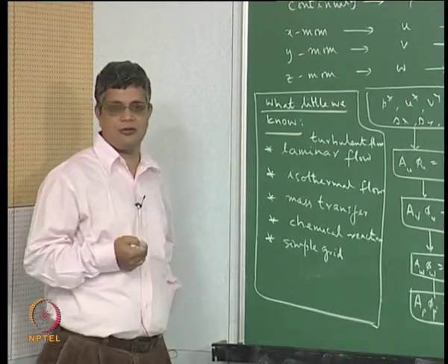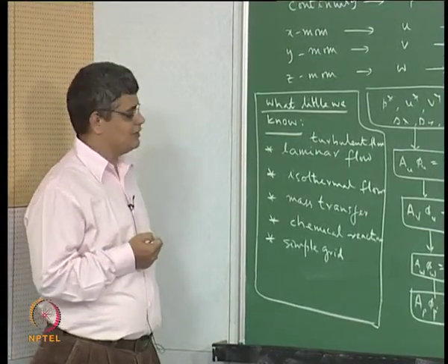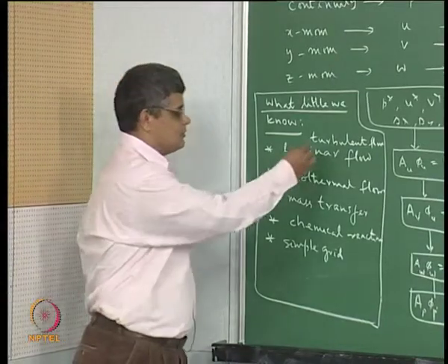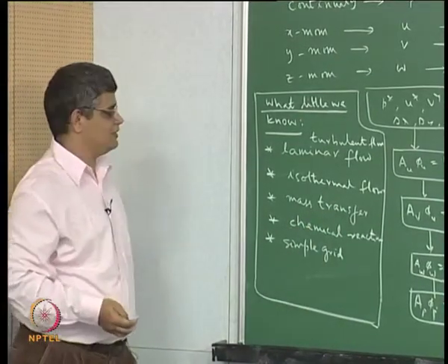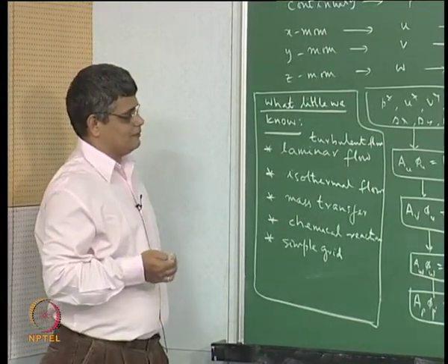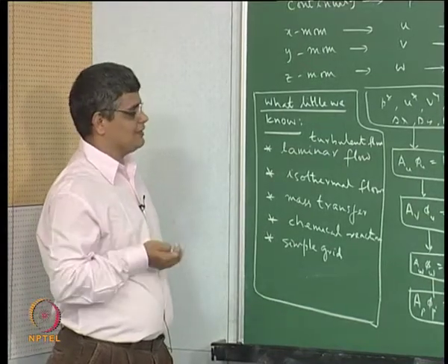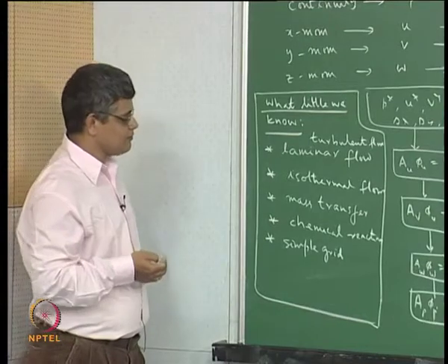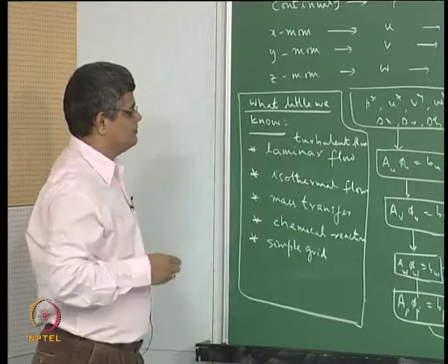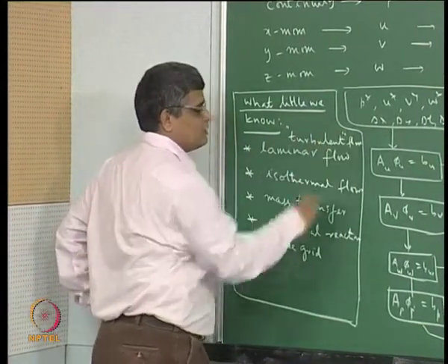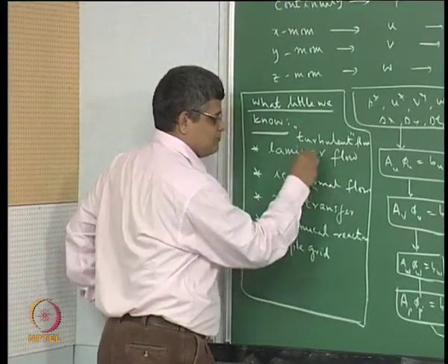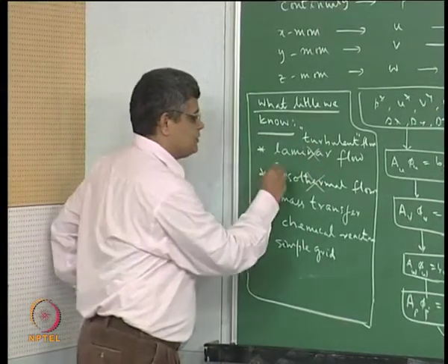Definitely it is one of the challenging problems, and definitely it has a lot of difficulties associated with it, and especially when you couple turbulent flow with chemical reactions, then it becomes really a humongous problem which cannot be addressed in its entirety in all its complexities that are typically found in practical applications using CFD. Okay. So we need to make approximations and we need to bring in models. So we need to see how we can deal with turbulent flow within the context of CFD, and we can easily get around this problem of isothermal flow by including the energy equation.